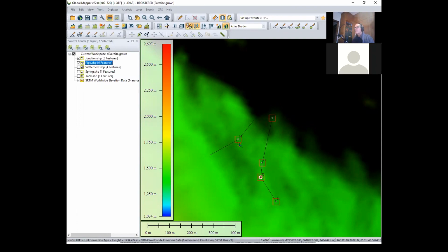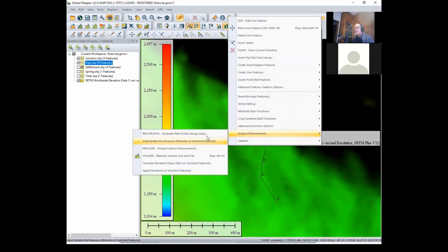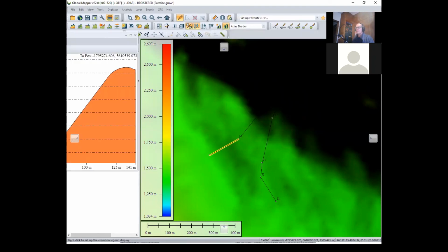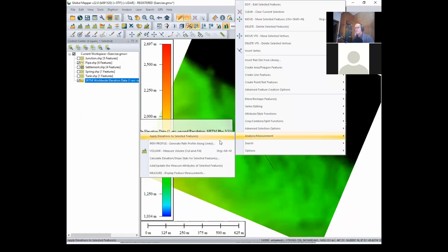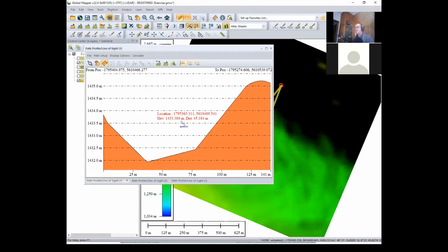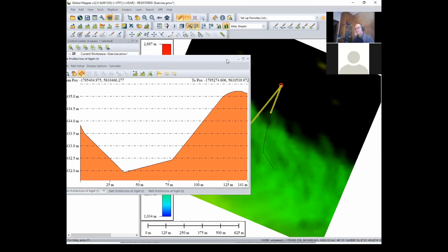And then additionally with Global Mapper, it's interesting that you have also the pipes. You can as well look at the section of the pipe, and this is important. You select the pipe, you right click on the pipe, and you can see the profile of the pipe. Analyze pipe profile. Then you see here the profile of your pipe. This is very important because at some point, for example, here you have a high point, you might identify the location where you can put an air valve or not, or a purge valve for cleaning the pipe.